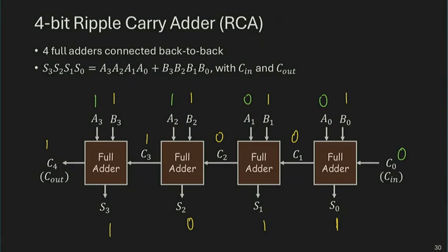So if I were to write those numbers in decimal, 1, 1, 0, 0 is my number 12. 1, 1, 1, 1 is my number 15. I would get an overflow, right? Because the result is greater than 15. So this should be an overflow condition for unsigned addition. And indeed, I do have a carryout. And for unsigned addition, carryout indicates overflow.